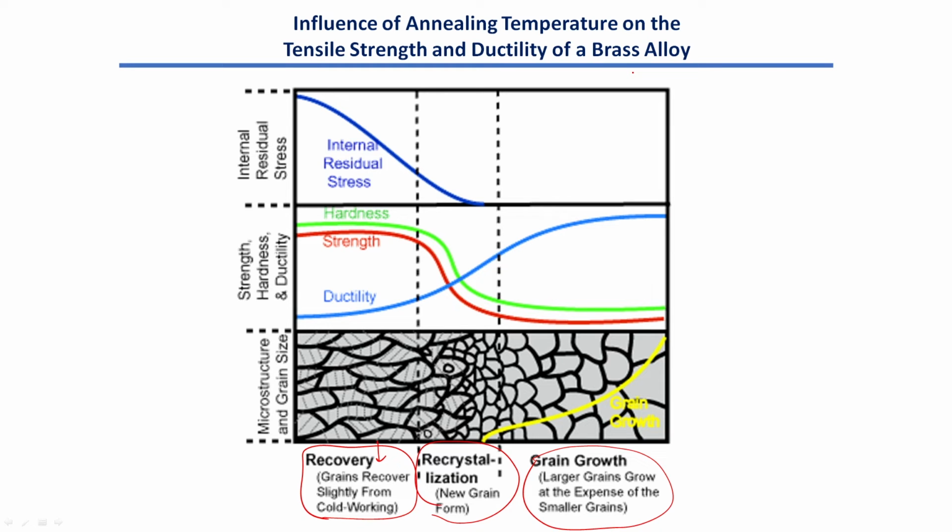Normally it has been found that recrystallization of any material happens at the melting temperature on the absolute scale divided by 2, that is Tm by 2. That is what actually happens in most cases. Now we know that Tm is well known and defined for materials. So simply by taking half of that on the absolute temperature scale, one can find out the recrystallization temperature.